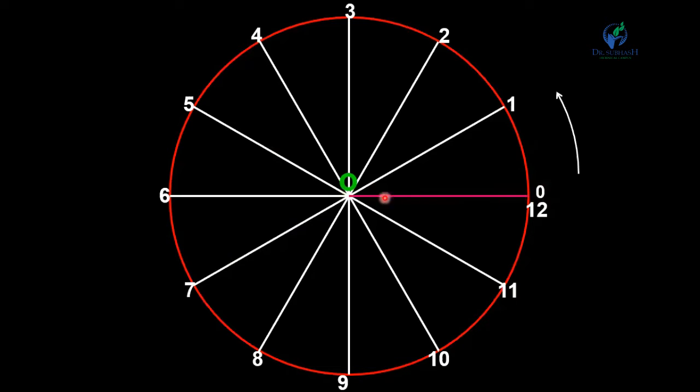Now divide this distance O0 into 12 equal divisions, so one part is 5 mm. Name them 0, 1 up to 12. Since we divided the circle into 12 divisions, we have to divide this line into 12 equal divisions. Now, if this point moves 1/12 of the revolution, it will be on this line. So take O as a center and radius equal to O1 and draw an arc up to the line O1. The intersection point is P1.